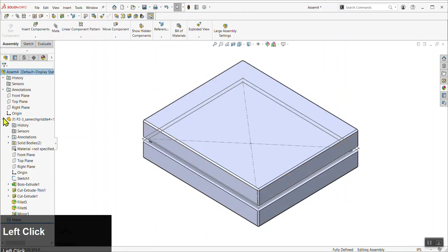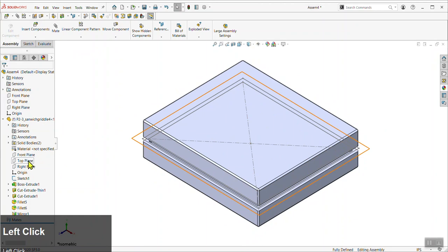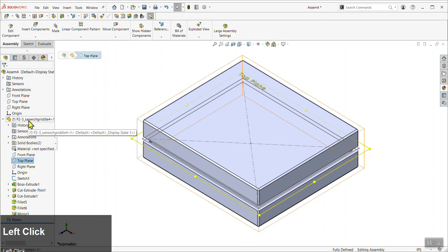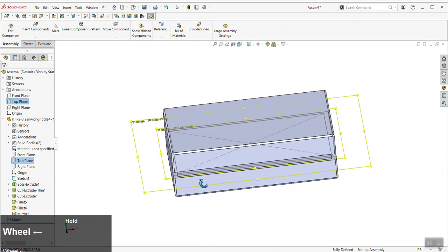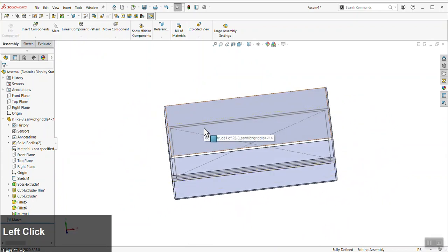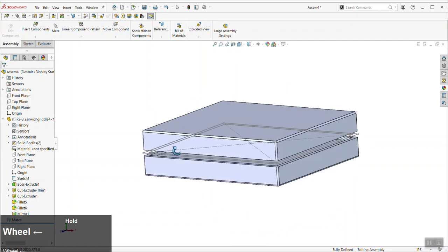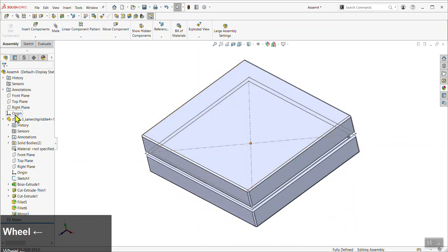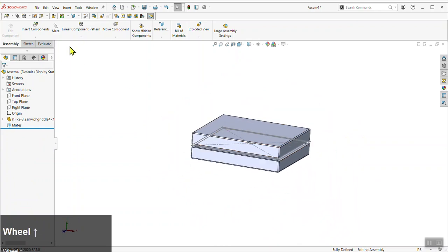And what this does by just clicking that green checkbox is it automatically aligns all the planes in the files. So the top plane in the part file will be aligned with the top plane in the assembly file. And this part is now our starting point, and the part that will define everything else added to this. So of course the point is to add other files.